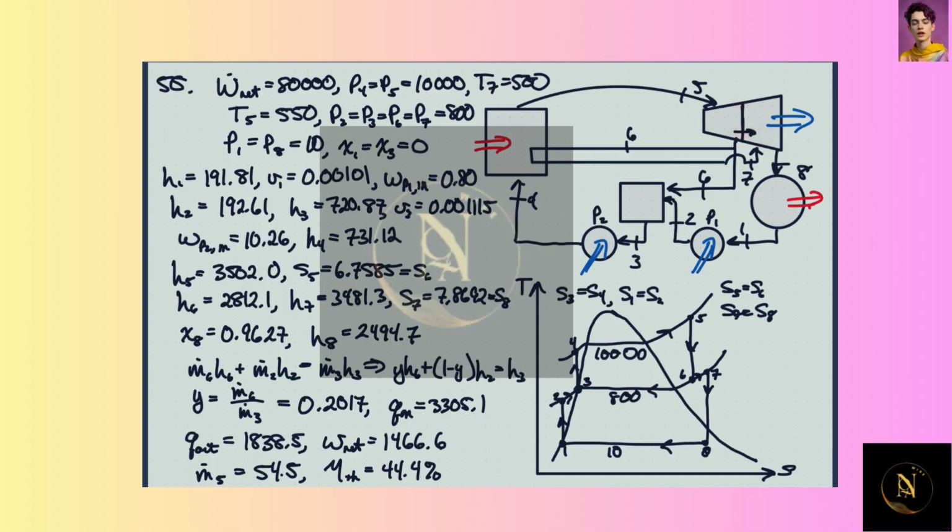We can think of this as a bleed with another input here, or as 2 turbines where we pipe the output of one directly into the input of the other. Anyway, I'm not sure exactly how they would do that in practice. Probably have 2 turbines because you can make each one a little more efficient based on knowing the pressures in it. A high pressure turbine might be designed a little differently than a low pressure turbine. So you'd probably have two different turbines and feed the output of one into the input of the other. Okay.